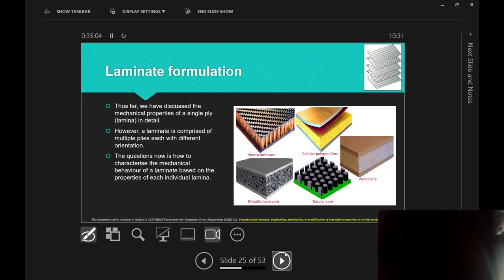All different fibers. So far what I've been saying is about one of these in 1 and 2 direction and x and y direction, and the x being my applied load. So I don't have to worry about that 0 degree because 1 and 2 is the same as x and y. There is no transformation. You can transform it, but you'll get the same stiffness matrix.